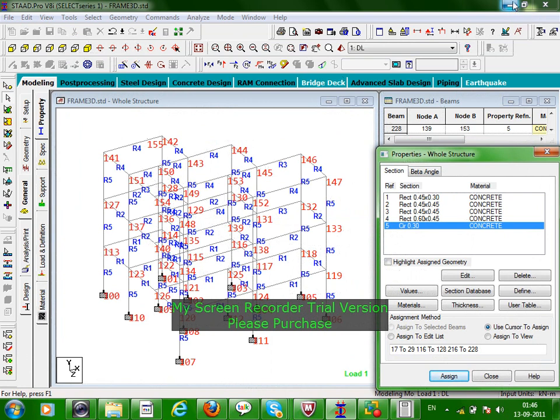What is that orphan node? Orphan node is an unconnected node. So this is a common error generated due to an unconnected structure. In the previous version, it would tell you that a parallel structure exists. Now this is revised, that an unconnected joint is there. In version 8, this is slightly changed.